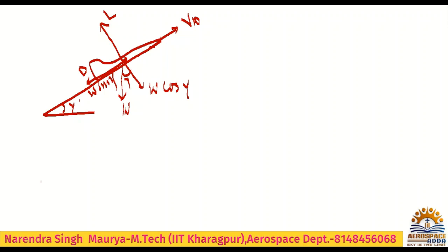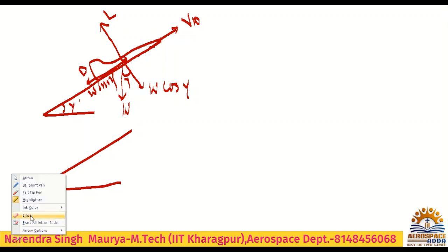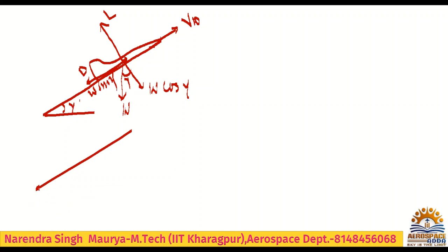And another thing, I will draw another diagram, triangle based, so that you can easily apply the trigonometric relation. That's the only reason. So here you can apply trigonometry. Check, this will be the climbing angle. What is this component? It is nothing but V infinity. Climbing means it is gaining altitude, so it will have a vertical velocity also, and that vertical velocity will be in the upward direction, obviously.